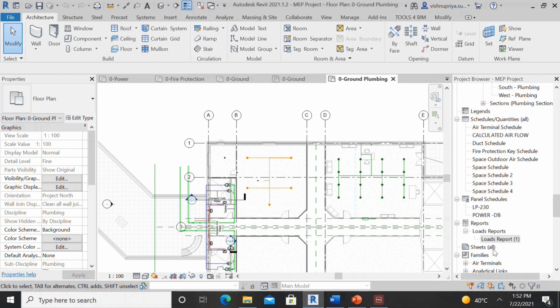You can do the coordination daily, and later on you can take it into the Navisworks software. From there you can do the coordination again if you want. Then a very good report can be created with pictures. But editing is not possible in Navisworks. Editing is possible in Revit only. Navisworks is the software that project managers or coordinators can use, project managers for review purposes, and coordinators for clash detection and review.